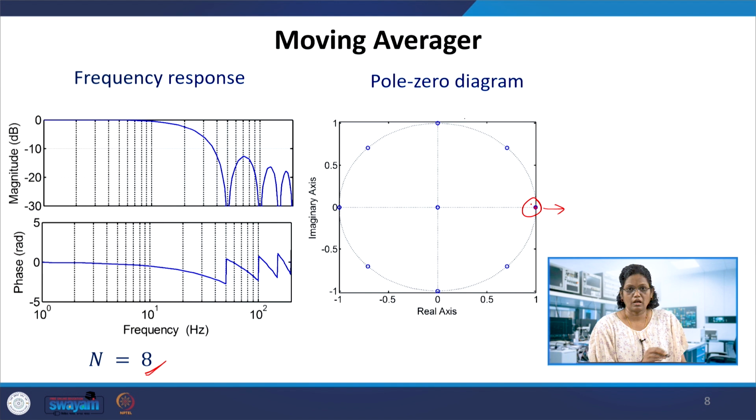That's how you have the output sequence which gives only DC, and the fundamental and second harmonic are removed from the input signal. If we take the frequency response, shown here on a log scale of 1, 10 and 100, with the frequency scale in hertz, it is tuned to 50 hertz, that is, fs is adjusted in such a way that the fundamental is at 50.